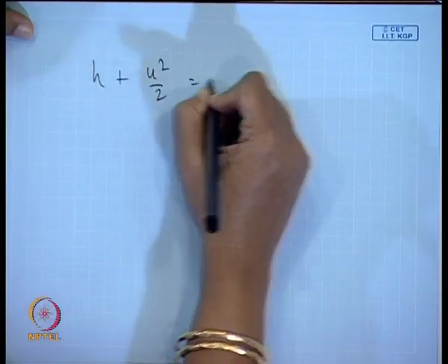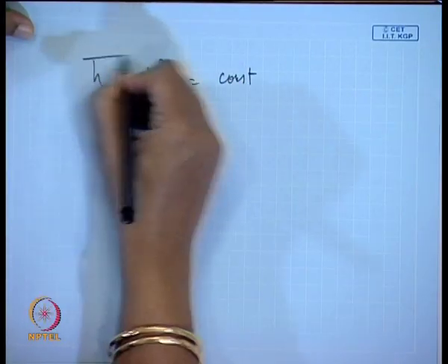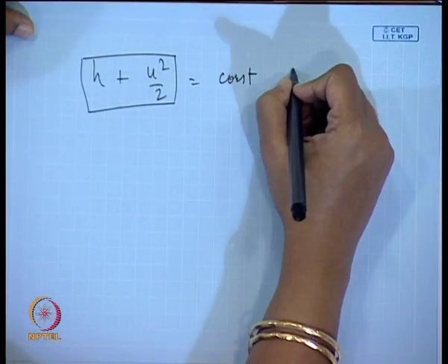How did I define the stagnation property? It is those particular properties which are formed when the fluid ceases to move or when a fluid is brought to rest isentropically. You agree? Do you get the point? So, therefore, we can write it in this particular form that for all these circumstances, for adiabatic flow, this particular term is constant.